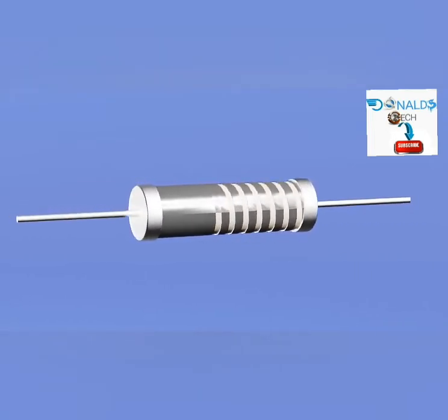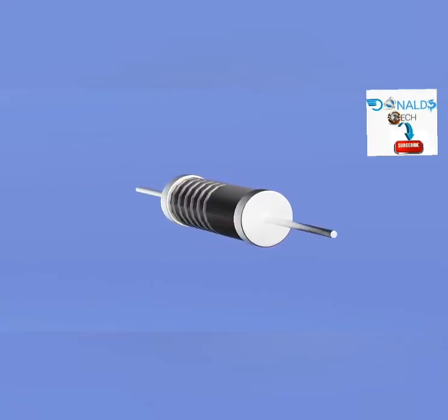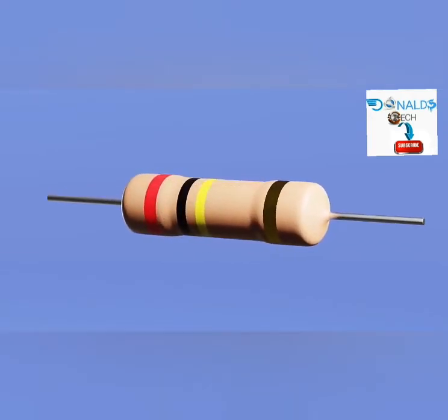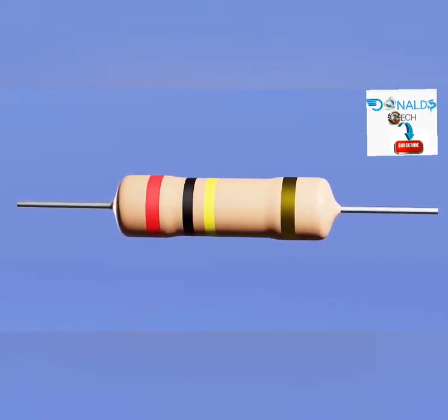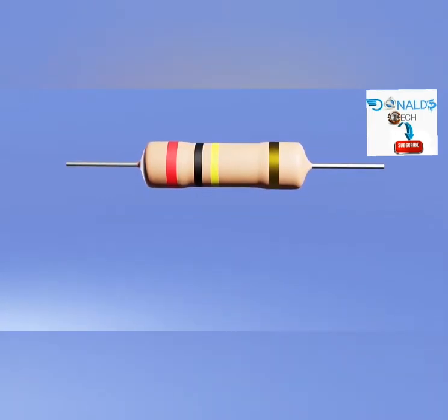As generally these resistances are so small, it would be quite difficult to print what their value is. That's why a color code was invented, by which we can know its value in ohms, even without numbers. For example, this is a resistor of 200 kΩ. The way to read its value is as follows. The first and second bands correspond to digits from 0 to 9, in this case red is 2, and black is 0. Then, the third band corresponds to a multiplier to avoid the need to put many black bands when representing large values. In this case, the yellow band means that you have to multiply by 10,000.